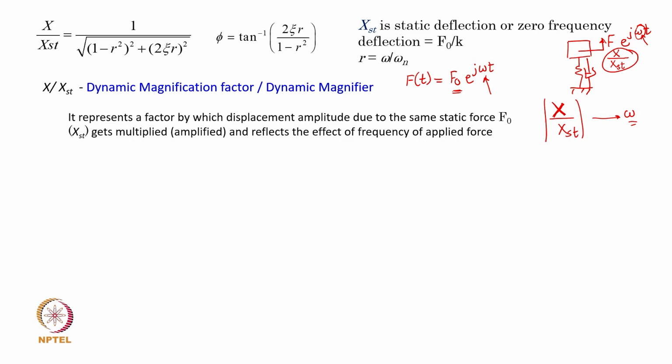So, the examples that we considered earlier of a rotating shaft actually will not apply here. The reason is that the force amplitude itself is a function of frequency. So, the amplitude will keep on changing, but as a hypothetical case, let us assume what response variation we get by assuming, for the time being, F naught being constant. We are definitely going to consider the case where F naught is a function of frequency of rotation.